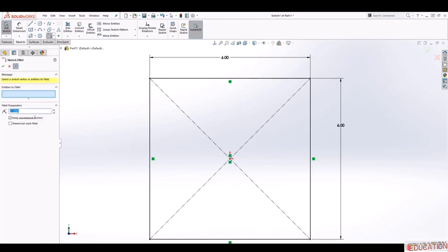And in this fillet, let's make it 0.5. So that is pretty much, you input your fillet size, which is 0.5. And now to add the fillet, you know what, let's make it 1, so it's big enough so we can see it. So what you would do is, to add a fillet between these 2 lines, you can click on this line and you click on this line and you press OK, and your fillet has been added for the 1.